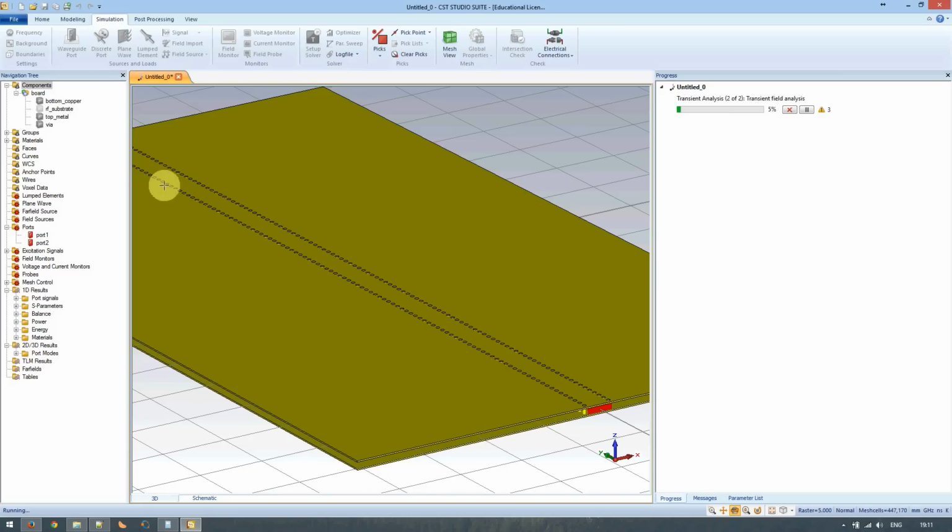It does a numerical technique based on Maxwell's equations, and it waits for the signal to die down past a certain threshold. So that option that we had, accuracy minus 30 dBs, it waits until the signal in all the cells is 30 dBs lower than the amount of energy that you put in at the front in the beginning.